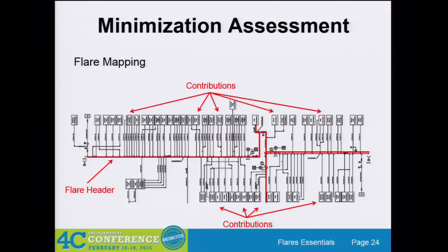It even includes things like sweep gas additions, and I believe there's an analyzer shelter on here too. It just shows you that they've thought about everything that is going to their flare. When you do it spatially like this, it also gives you ideas, like instead of having just one flow meter, maybe I put a couple of flow meters on some of these branches.